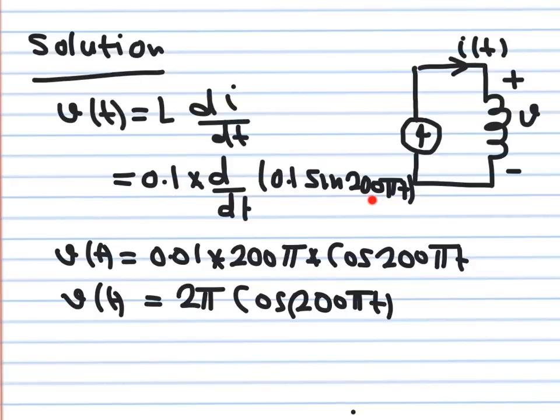Okay, you can see the frequency itself. This is omega. This is sin(ωt). This omega here, which is the radian frequency, in radians per second, does affect the amplitude of the voltage. So this amplitude of voltage depends on two things: on the value of the inductance, and on the frequency of the current waveform. Okay, so what does this mean?